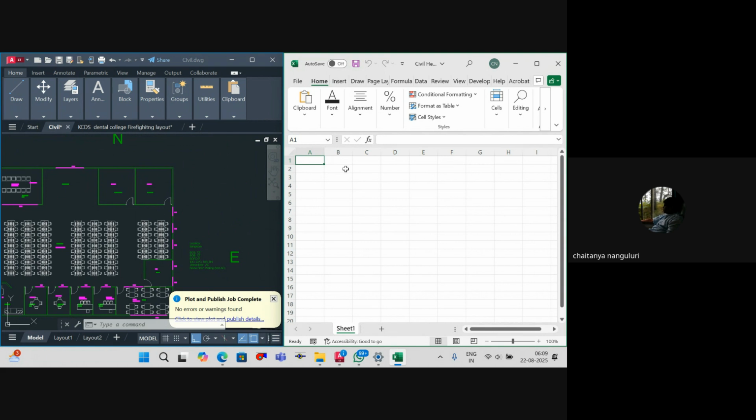So first we'll calculate the ODC. I'll write this as dry bulb temperature, then wet bulb temperature, then relative humidity, then humidity ratio. This is your ODC, outdoor conditions. This is your IDC, indoor conditions.